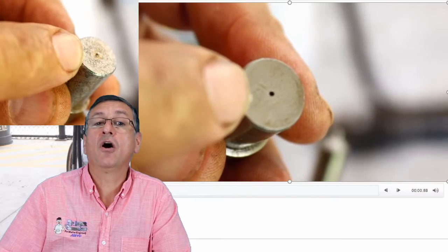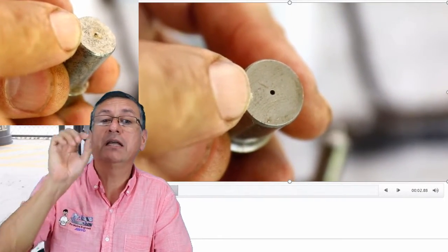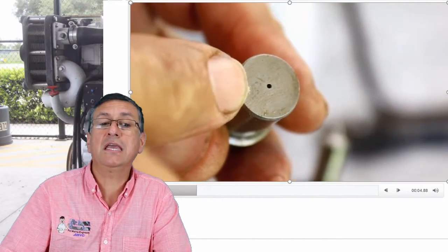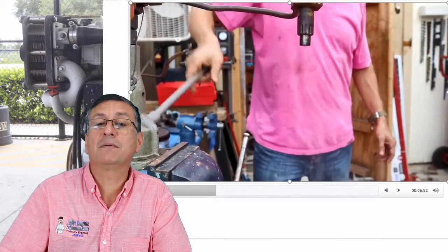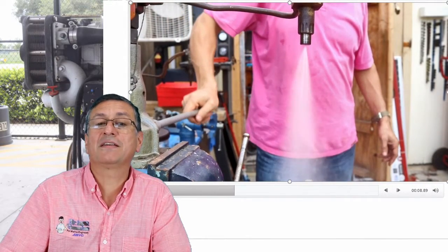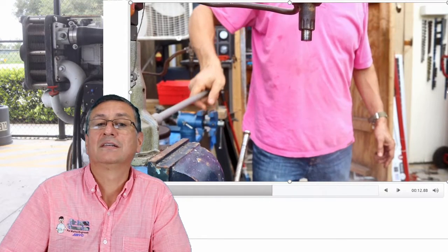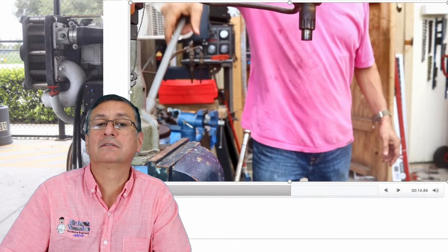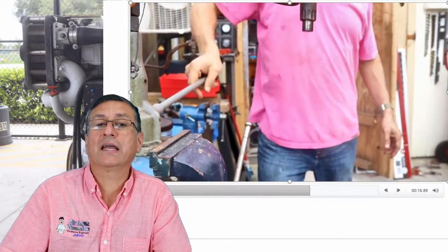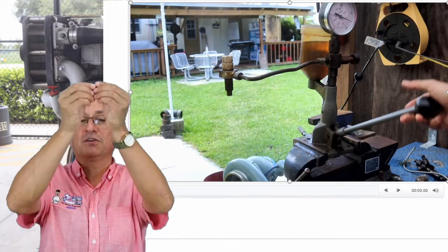Look, this is the hole where the pintle enters. In this moment the pintle is in. This is the pattern. It's directly down. Correct. And normally that injector opens at 2200 psi. This is the pattern. The injector sprays directly down.